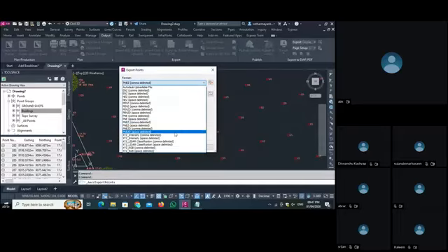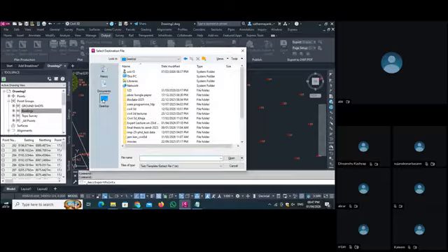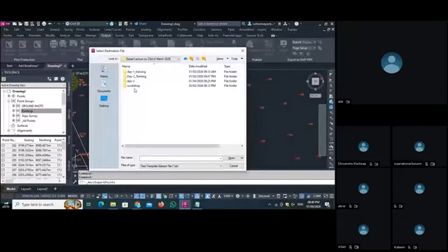as we have the format PNEZD comma delimited description file. If you want to describe the file, where you want to save this, let's save these points here in our day 3. Okay, file name, we give the file name as we imported, building points.